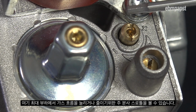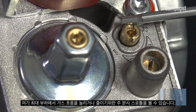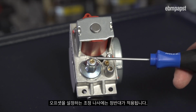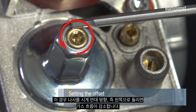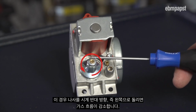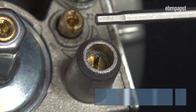Here you can see the main injection throttle for increasing or reducing the gas flow at full load. Turning in clockwise direction, in other words to the right, reduces the gas flow. The exact opposite applies to the adjusting screw for setting the offset. In this case, the gas flow is reduced by turning the screw in a counterclockwise direction, in other words to the left. This is the pressure test nipple for measuring the offset pressure.